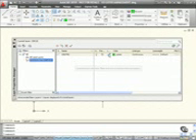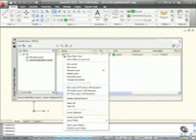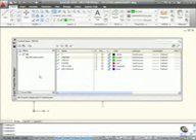Now that's based on those settings that I set here. As you can see, it's evaluating new layers when added to the drawing. So what it's doing there is letting me know that this is an unreconciled new layer. What I'm going to do now is just right click on it, and you can see there I can reconcile the layer. That disappears and it goes into the group of layers that have been used, the All filter here.